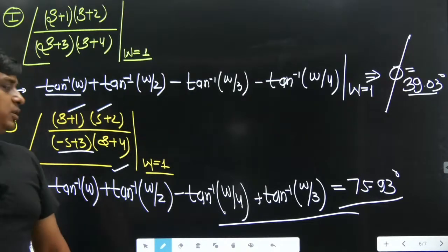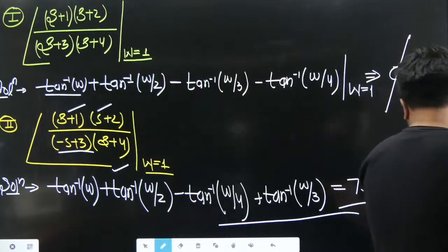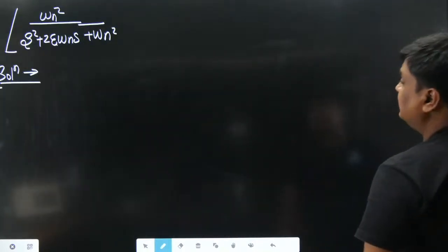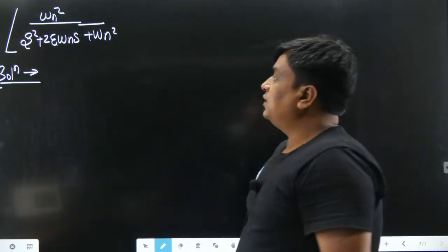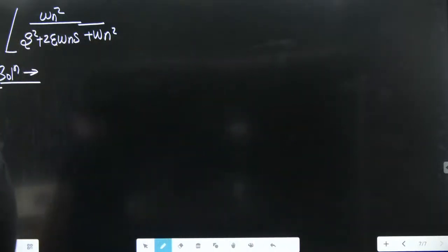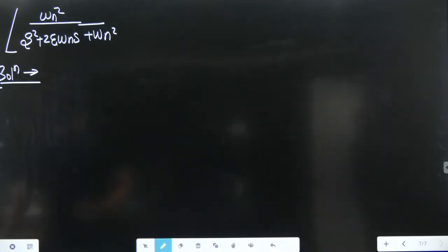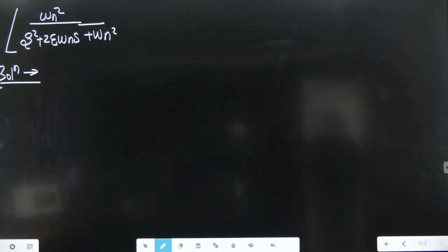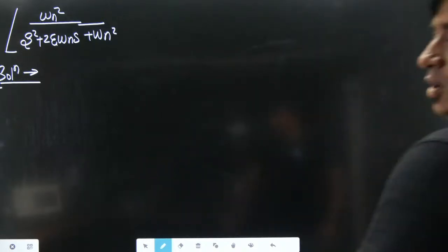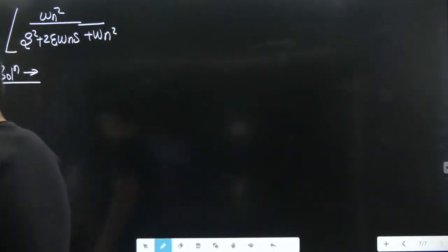Anyways, when we discuss the Nyquist plot, which is an extension of the polar plot, the omega still starts from 0 and goes till infinity. Tell me how much angle would be offered by this system. So it is tan inverse of omega T by alpha.